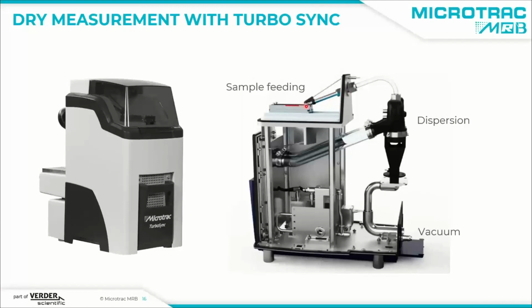So the sample is aspirated into this pipe here and then transferred to the dispersion area, where you can use some compressed air to introduce shear forces and to separate the particles from each other. So then you have a well-dispersed sample. The measurement is taking place here, and then the sample is carried out of the system by a vacuum that is connected to the analyzer.